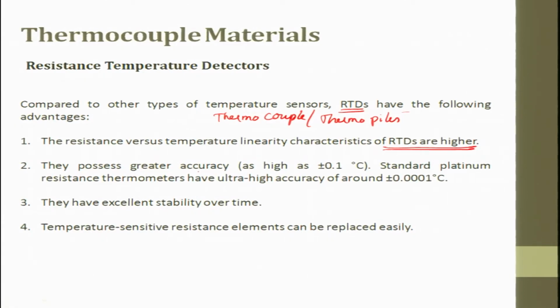They possess greater accuracy compared to the other two techniques. They have excellent stability over time. Then temperature sensitive resistance elements can be replaced very easily, which cannot be done with the other devices, where wiring has to be done. These are the advantages of using RTD over the other temperature measuring devices.